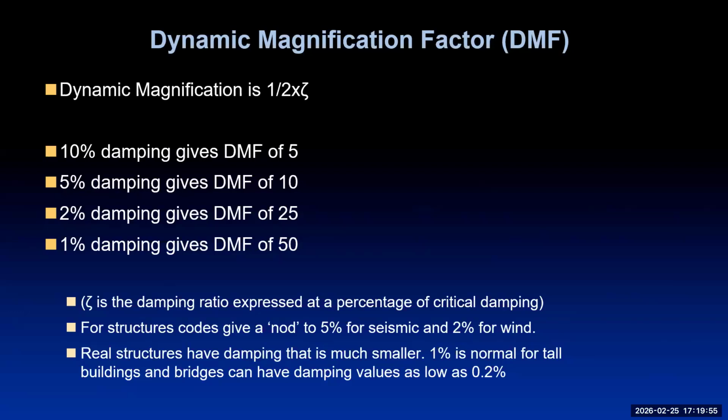But, and there's an important but there, the fact that you have very low damping and it's a nonlinear response, and it can increase as you go up, all that means is that if you have low damping to start with, you're going to get up to a high amplitude much more quickly. And that 5%, if it aligns with the resonance, may not be conservative. They're using a probabilistic approach with these estimates because they're looking at it from the context that the probability of hitting an exact structural resonance during a random event like a wind or seismic event is rare.